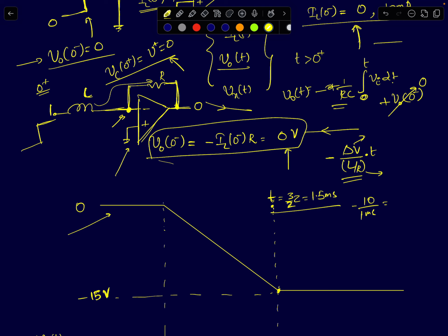Okay, so remember, capacitors accumulate charge. They tend to accumulate charge. So if you push a constant current, the capacitor voltage will integrate the current. In this case, the inductor's current will start increasing. Its current is increasing because you have applied a voltage across it. Since you have applied a fixed voltage across it, the current will ramp. It will slowly start building.